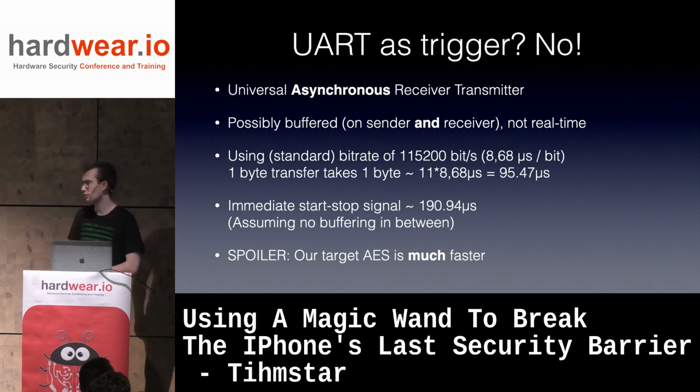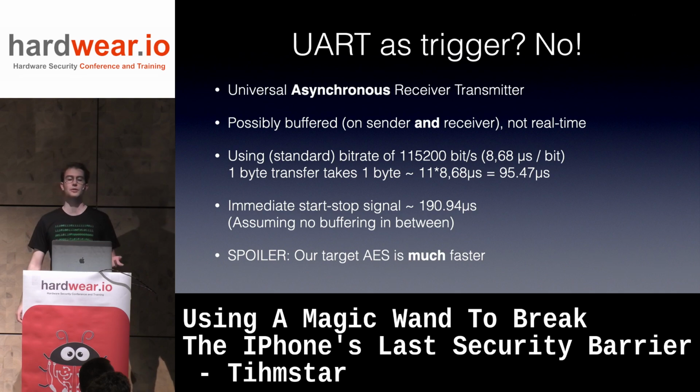Well, how about triggering our scope measurements with the UART? Well, no. UART stands for Universal Asynchronous Receiver and Transmitter, and the asynchronous is a problem because it's also possibly buffered on sender and receiver side, and it's definitely not real-time.